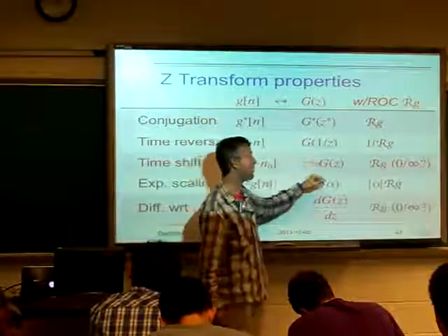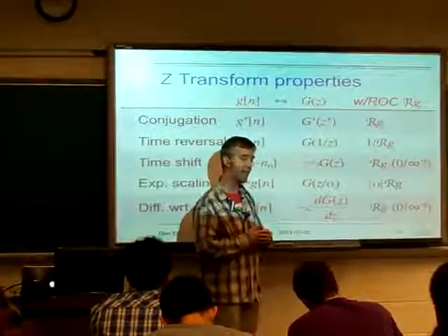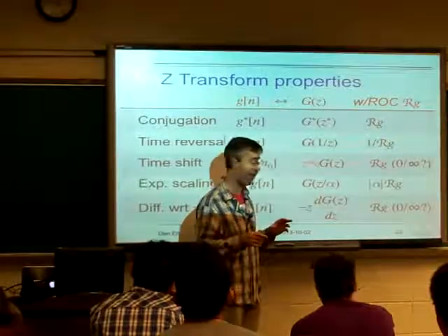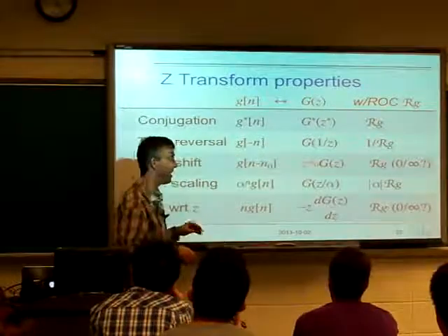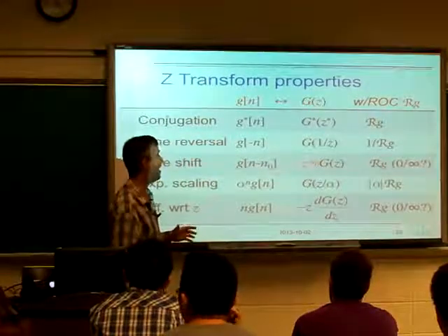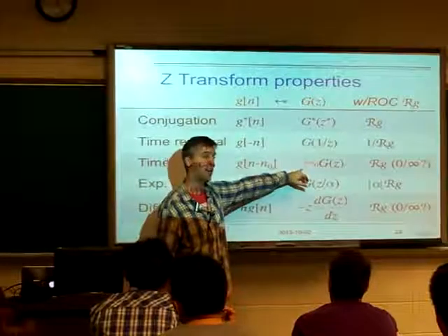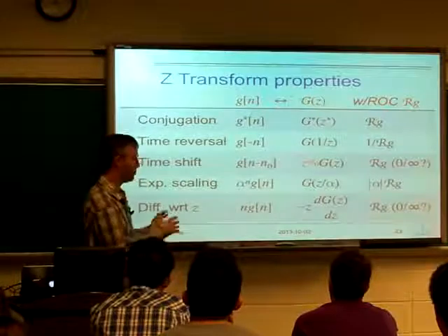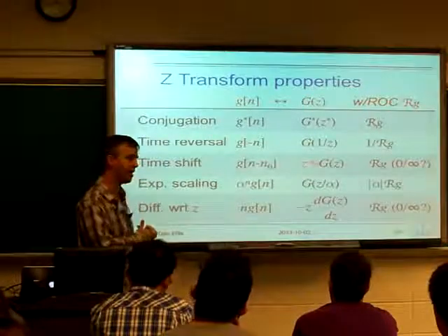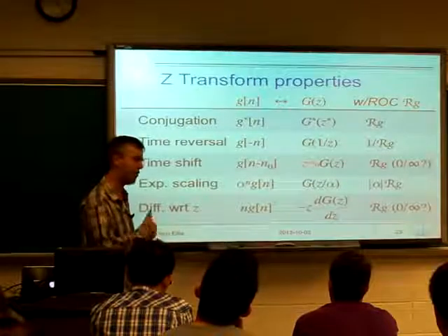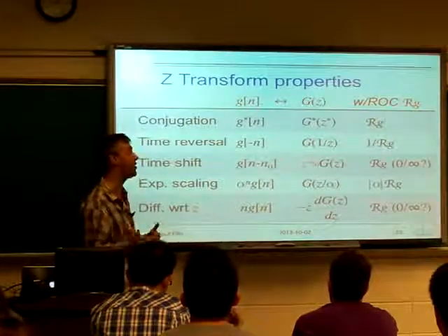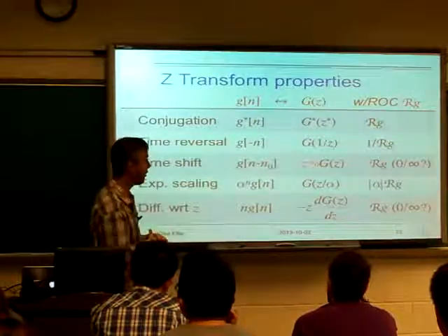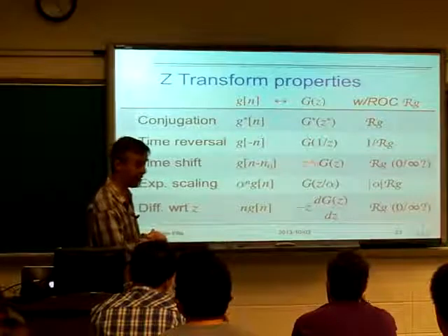And we notice here that when we're drawing our block diagrams, if we wanted an n0 step delay, the way we draw that is a box with z to the minus n0 in it, because in z-transform space, a delay is just multiplying the z-transform by some power of z, the power corresponding to the number of steps delay. So that's why we use that convention, and that's one of the nice things about the z-transform, that now it turns delay into multiplication. So that other thing we might want to do in our blocks, we can quickly turn into just a simple algebraic operation.